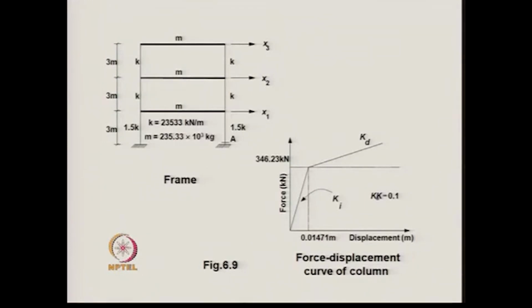And unlike the perfectly elastoplastic case, we do not consider an ordinary hinge to exist at the point of plastification for subsequent calculation.